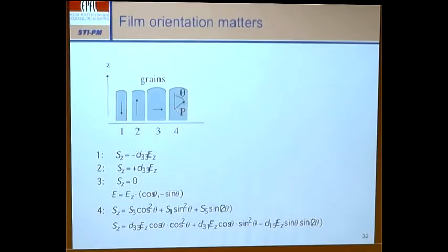When we have a polycrystalline material, it's possible, of course, that not all grains have the same orientation, or we have domains with different polarization directions. It's clear that when you have polarization down here and polarization up, like here, you get effects that are opposite in sign. If you have a mixture of these, then you may have zero effect in this direction. You may have a shear deformation, but not a step.